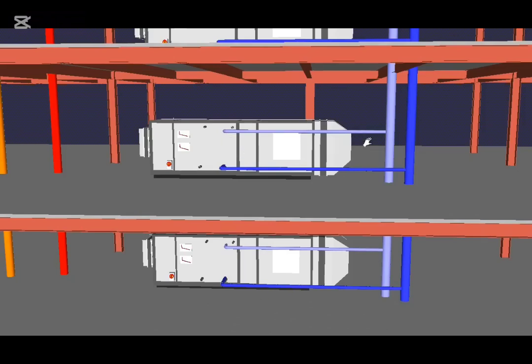So that rising temperature is the result of the air which is passing through this air handling unit cooling down. So the warm air enters, it hits this coil, the coil transfers its cool into the air, and the air transfers its heat into the coil. The air leaves at a lower temperature, and the water then leaves at a higher temperature.